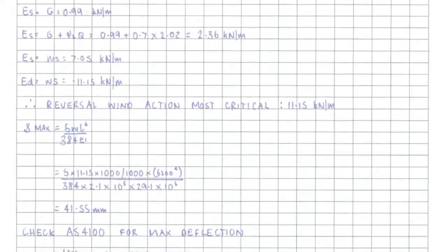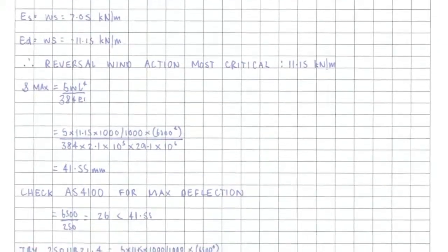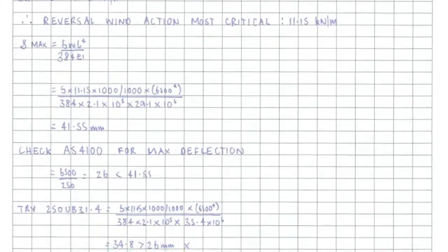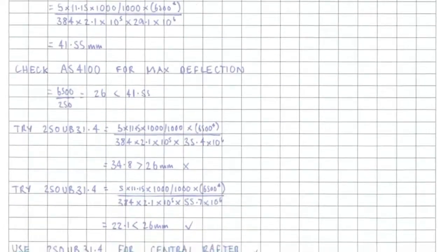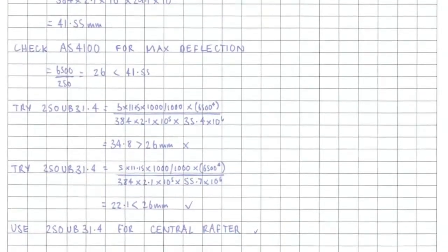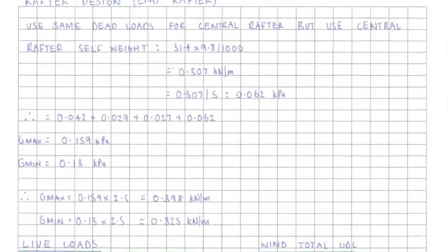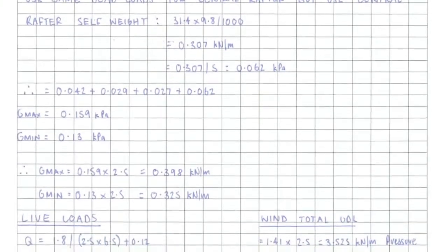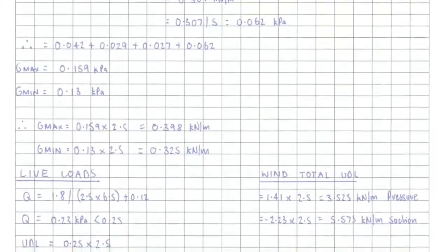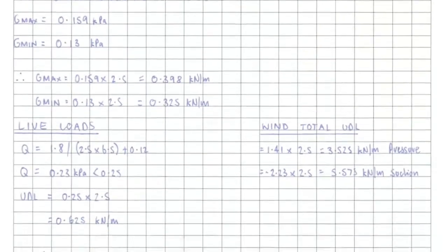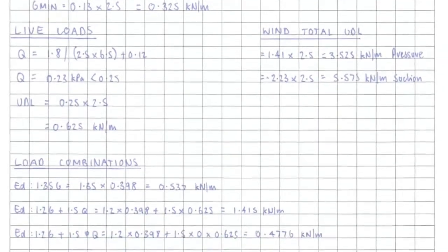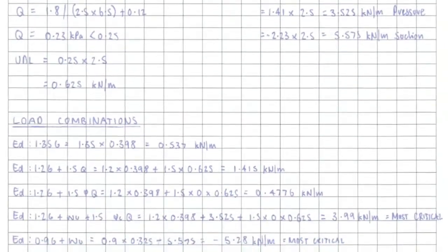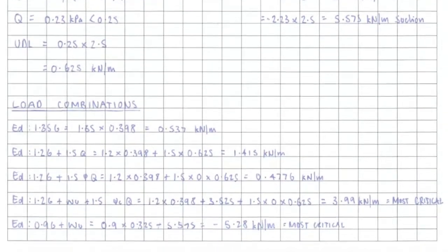When both of these met the requirements, it was then again serviceability that was done from Australian Standards 1170.0 for the maximum deflection allowed, which did take a few goes to reach a suitable member, as our chosen member sizes were quite insufficient to begin with, so it took 2 or 3 tries to find a member that had the capacity to withstand the deflection amount.